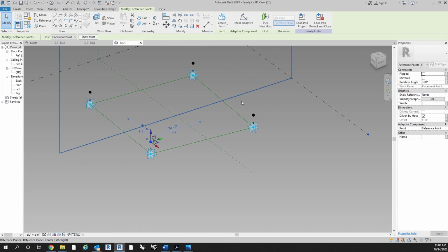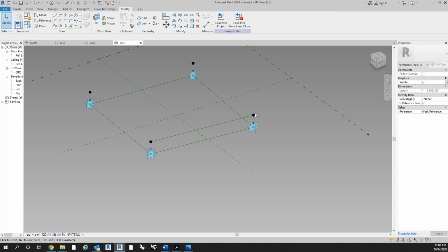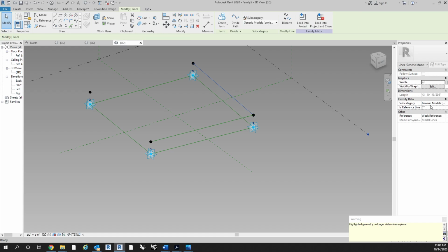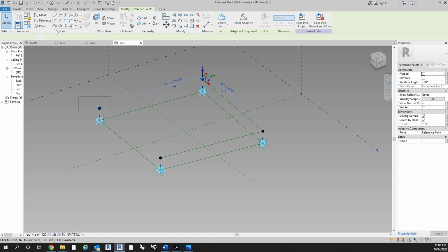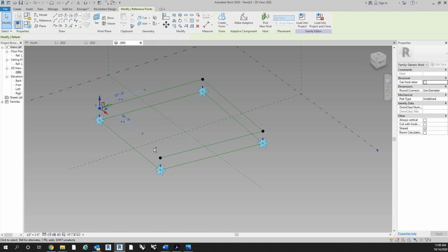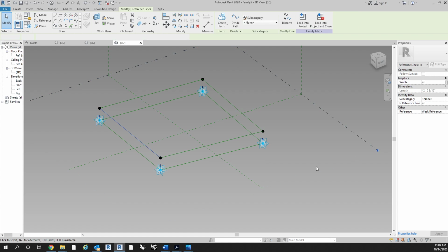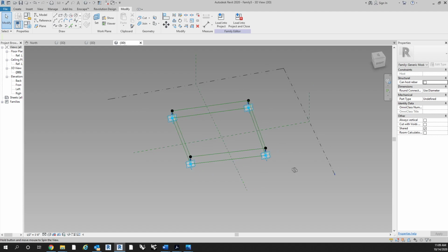What we'll do with these is literally the same thing that we did with the nodes, spline through points, make them a reference line, excuse me. There's a lot of repetition in this, but it's all important in making sure that the panel itself and all the geometry associated with it is adaptable and linked to those initial nodes so that they form and manipulate themselves to the surface.